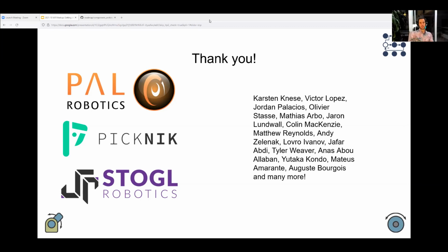Yeah, but usually, I have to say there are good examples, for example, PAL or similar, who are actually running on PCs or PC hardware in this direction. You can get some very good real time. It's a bit hacky. There is, I think, a good description for ROS1 about a KUKA driver with a preempt kernel, with which you achieve a lot already.